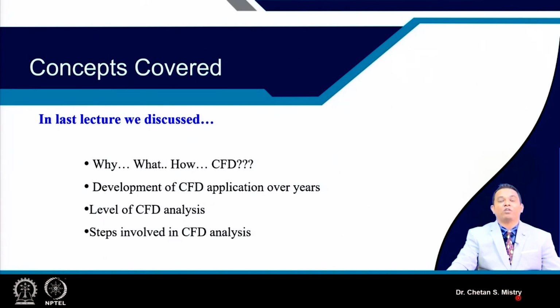Then, based on that study, the question is what exactly we are looking for. How is the flow behaving within the blade passage? Is it as per our expectation or not? That means we will be checking velocity components, flow angles, pressure distribution, and total pressure distribution.